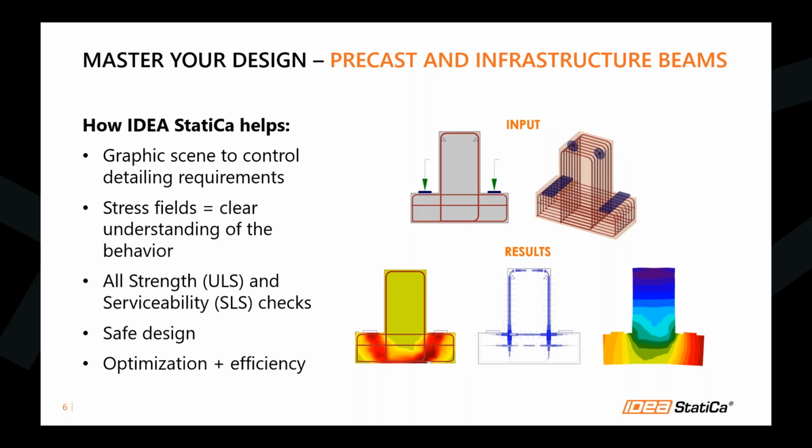So instead of strut and tie, another approach is to use the compatible stress field method and IDEA StatiCa Detail. Why? Because thanks to the graphic scene, you have control over the detailing requirements. You can display the structure either in 2D or 3D. So in 3D, you immediately see the placement of the reinforcement, to avoid any congestion. Because of the nature of the compatible stress field method, we work with stress fields, so we actually see the actual response of the structure.